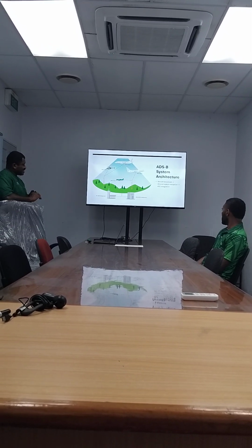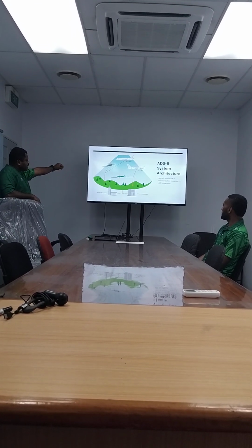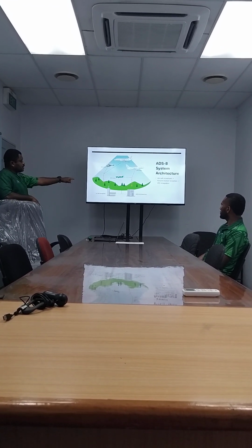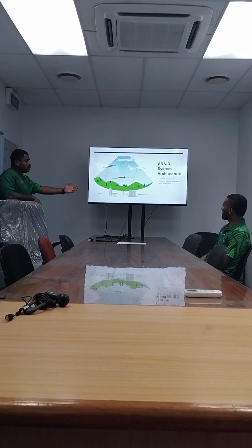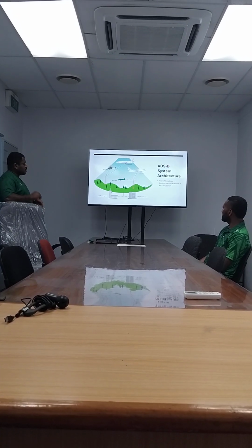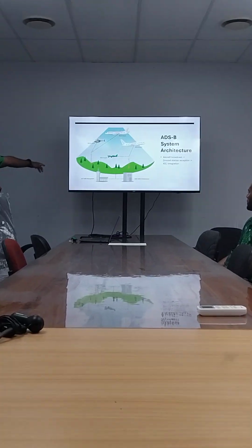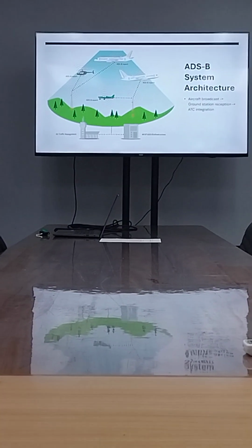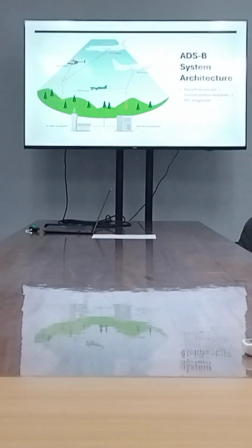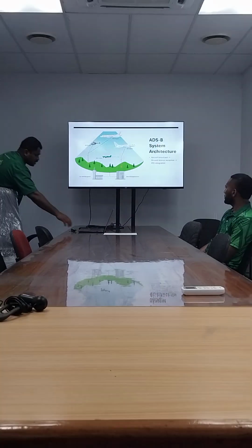All those data are sent through the ADSB data, received by the ground station, then processed and time-stamped by the particular ground station, and sent to the ADSB infrastructure, also known as the CPS, or Central Processing System. The main server gets the data, converts it to ASTERIX data, which is sent to air traffic management. And you see the display on the ASD or situation display of all the aircraft that are within ADSB coverage. We'll cover ADSB coverage in the next few slides.